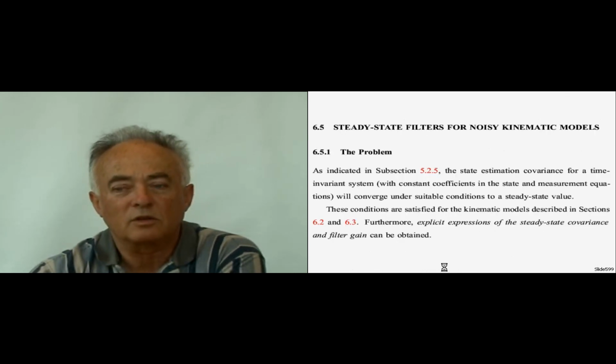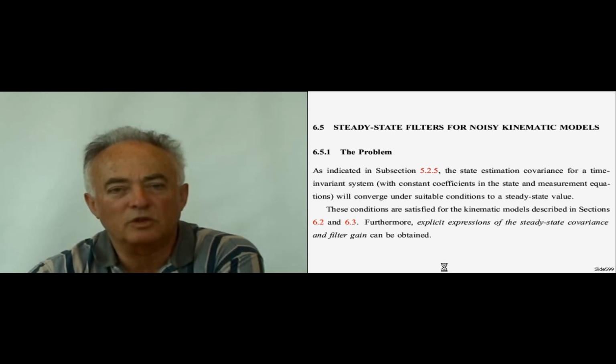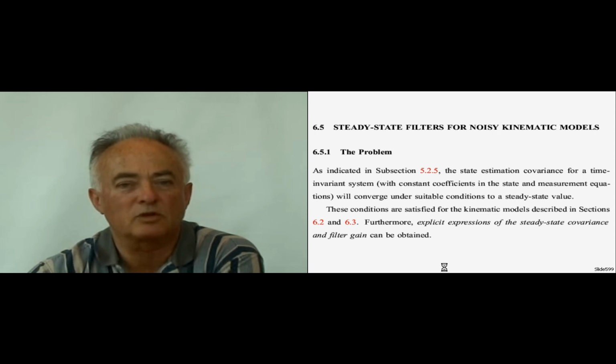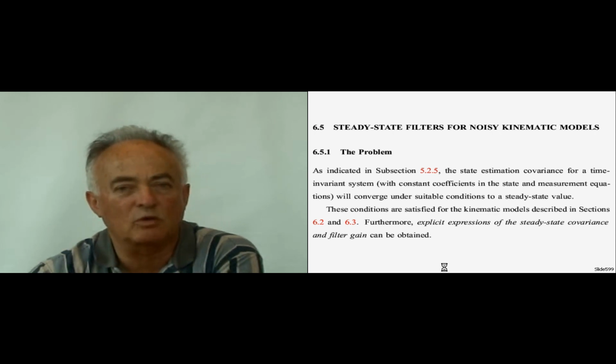Now, as I said, an important property of both of these models is that their corresponding Kalman filter Riccati equations do have a unique steady state positive definite solution, because first, the observability condition from the position observation for the position-velocity or position-velocity-acceleration state yields complete observability.